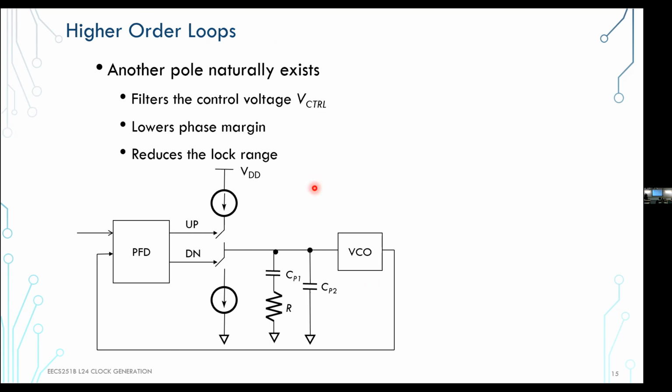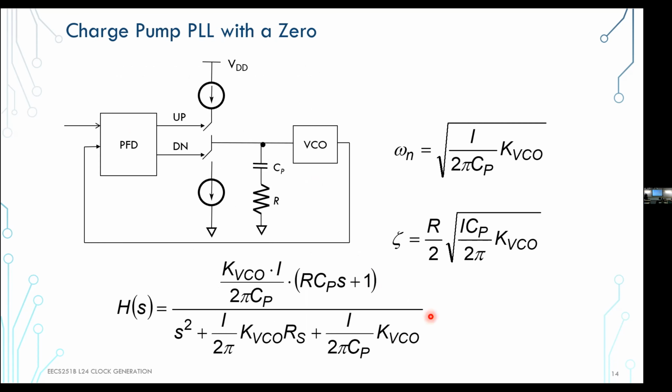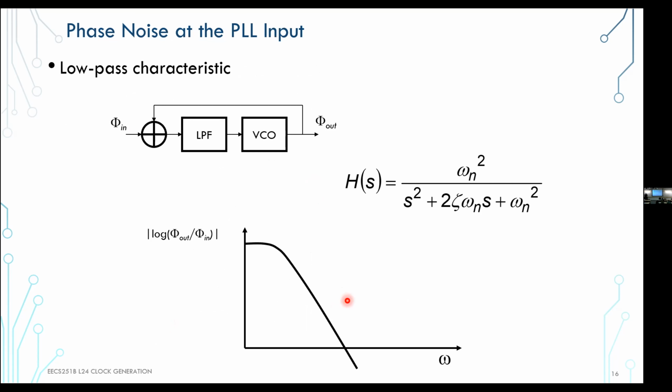And let's say, look at this overall transfer function, right? Regardless, even if we have a zero here or a second pole, it's going to be a low pass filtering type transfer function. How underdamped or critically damped or overdamped that's a choice for you based on these parameters here. So that may end up with a little bit of peaking here or not.